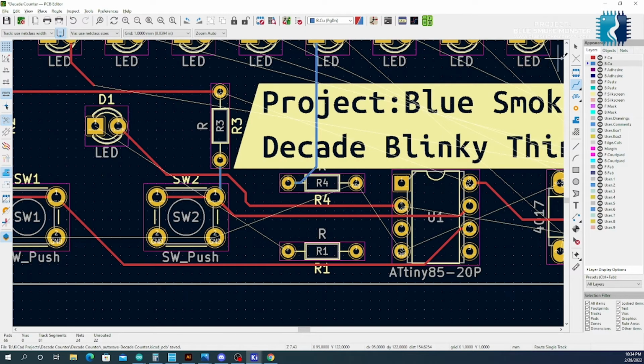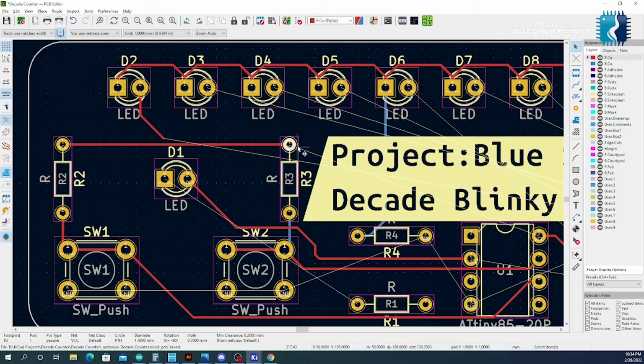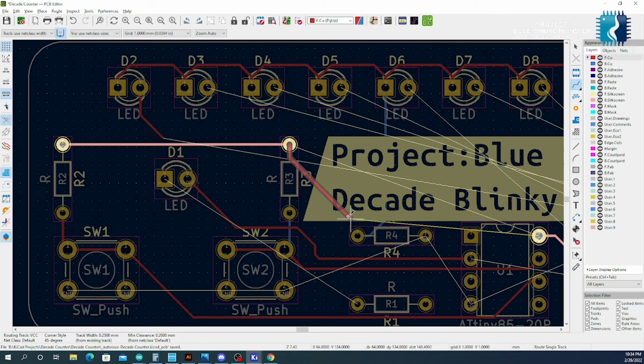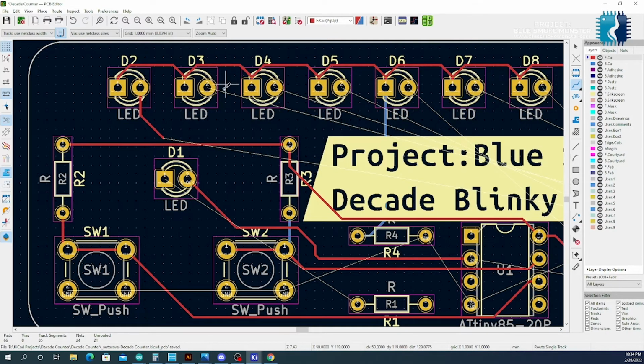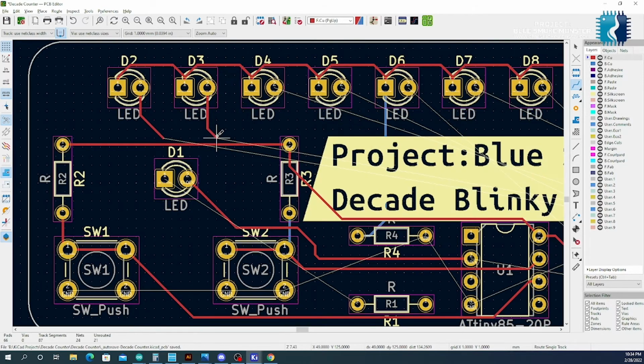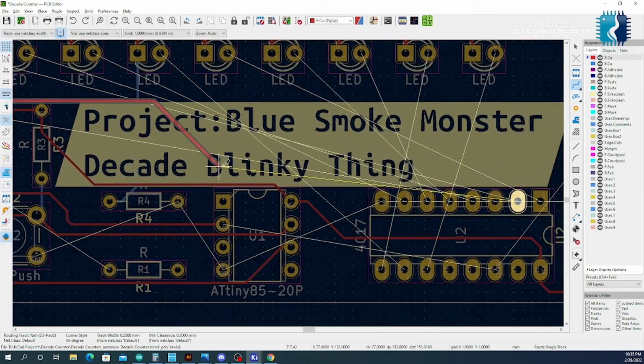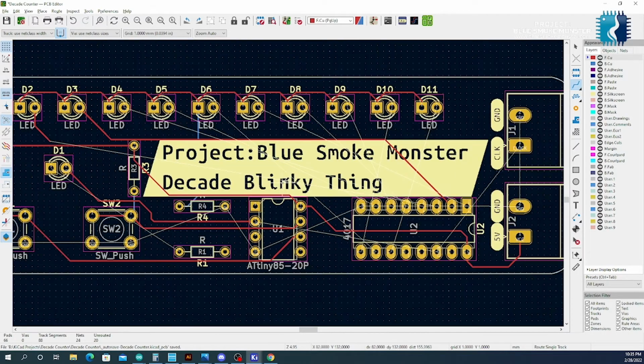Okay, that's better. So now, if I go to the top side, and I go here, that's my VCC line. Yeah, this, I think I'm gonna like this better anyway. Bring it to there, over and down. Now, from this one, let's just run it, and then we'll let the push and shove do its thing.